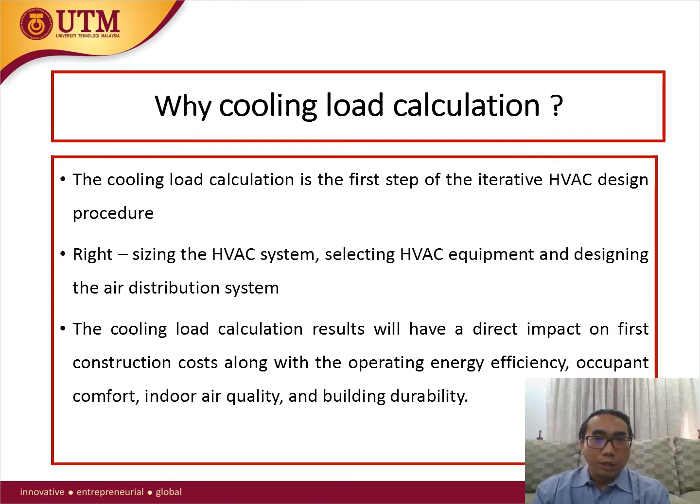Why cooling load calculation? Number 1, the cooling load calculation is the first step in the iterative HVAC design procedure. Number 2, right-sizing the HVAC system, selecting HVAC equipment, and designing the air distribution system. Number 3, the cooling load calculation result will have a direct impact on first construction costs along with the operating energy efficiency, occupant comfort, indoor air quality, and building durability.